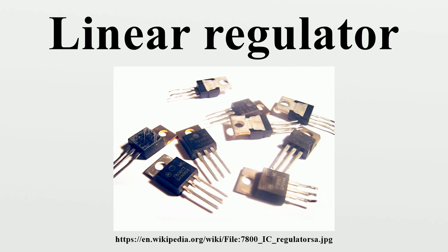By switching in different Zener diodes or resistors, the output voltage can be adjusted in a stepwise fashion. A potentiometer can be placed in series with the ground terminal to increase the output voltage variably. However, this method degrades regulation, and is not suitable for regulators with varying ground current.